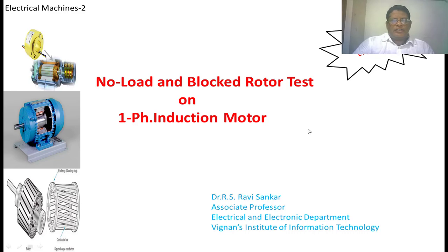Welcome back to the class on the no-load and blocked rotor test on a single phase induction motor. Generally, we conduct a no-load and blocked rotor test on a single phase induction motor to find the equivalent circuit parameters of the induction motor so that you can do the theoretical analysis on the single phase induction motor.